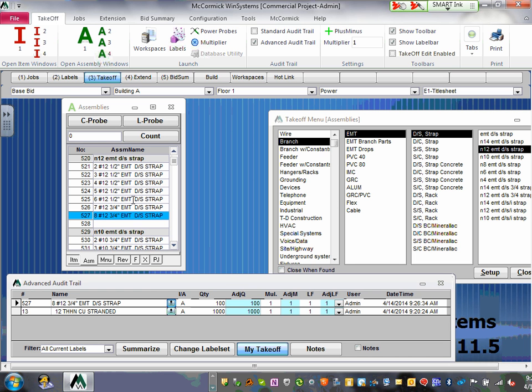Still have another 8 for future use. But you don't want to load it to 16 because you have voltage drop. You have derating factors. You have to derate that. You start derating, right? So 8, perfect. Okay, so that's what we did.